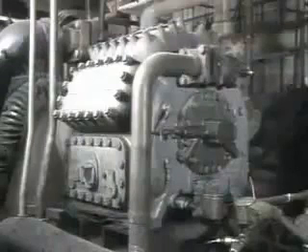One place where this is a problem is in the evaporator. When refrigerant flow through the evaporator is too low, less heat will be removed from the substance being cooled. This will cause the temperature of the substance being cooled to increase. The compressor may also provide an indication of a low flow problem.